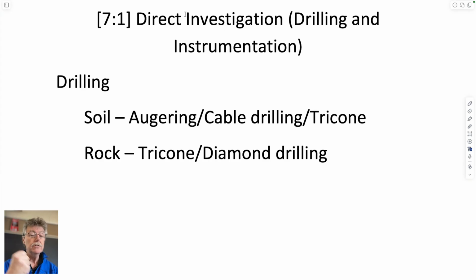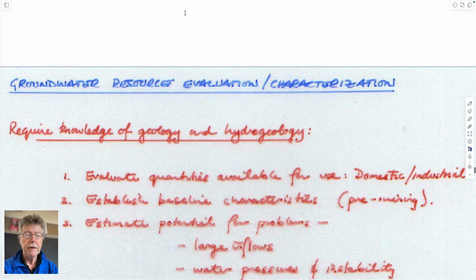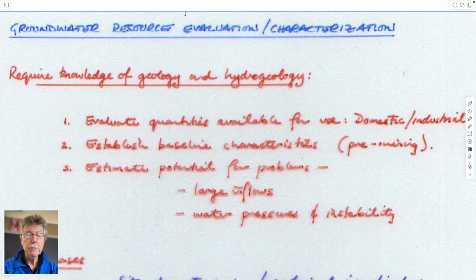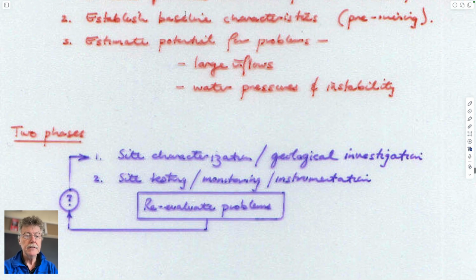Maybe retrieve samples that you can do some tests with. If you need to do tests, we've already ascertained, I guess, that it's not very helpful to do tests on samples for dispersivity because that's a function of the entire aquifer, not just a point measurement. And so we might think about doing that. So there's a bit of verbiage on what to do. We want to figure out the parameters we need to know. What do the bedding look like? Which one's a high permeability? Which one's a low permeability? Where is the source? Where that might travel? And what might be the characteristics that define how quickly that material might be traveling downstream?